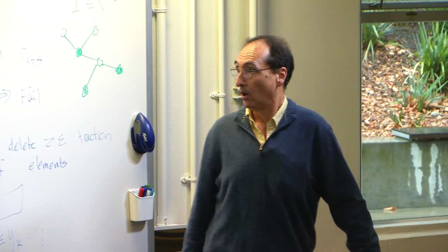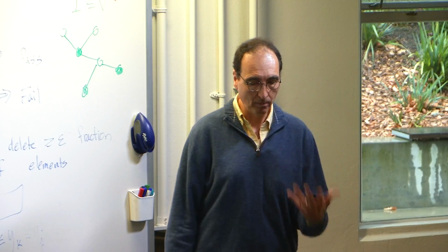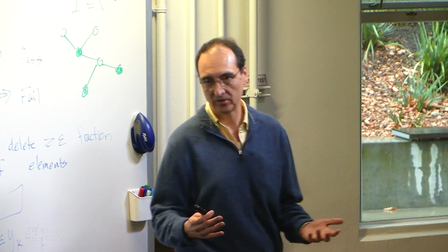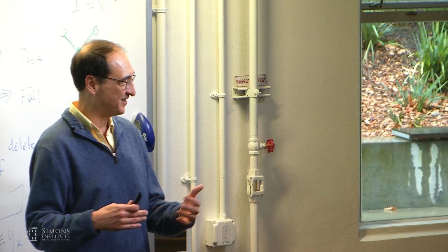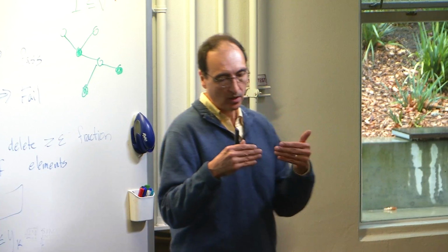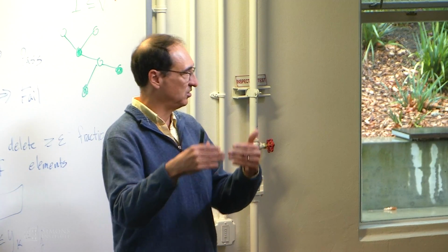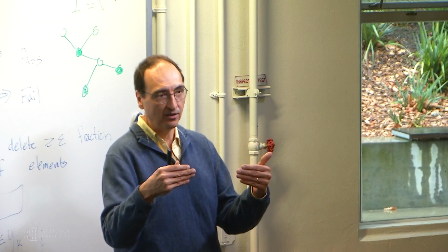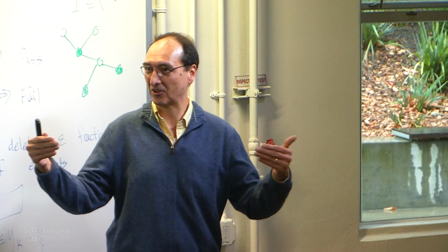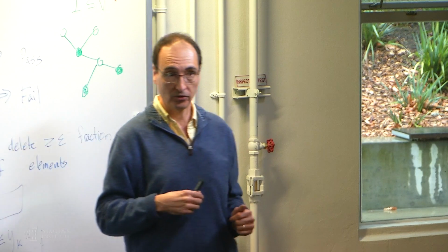So these PID controllers turn out to be ubiquitous because they do lots of things very well. They're in all of the heating systems. They're probably in your battery power supplies and lots of other places. And they're a way to allow the system to take into account constant disturbances, or maybe your car is heavier than it normally is. You'll compensate for that too. It's all sorts of uncertainty that gets compensated for with an integral term.